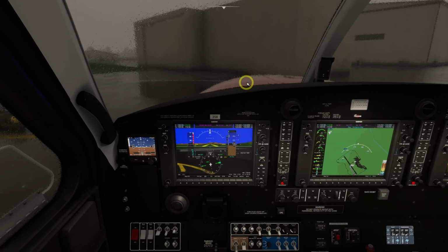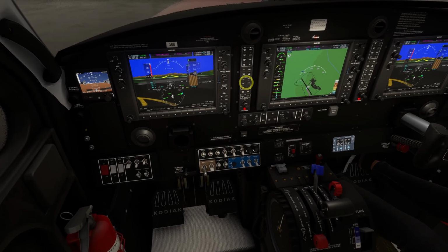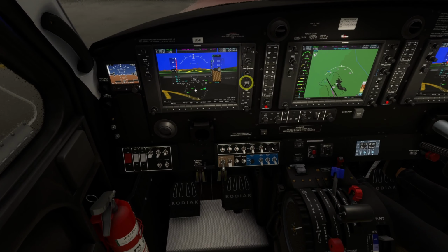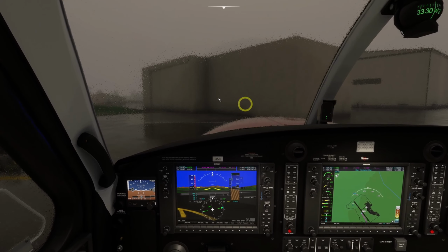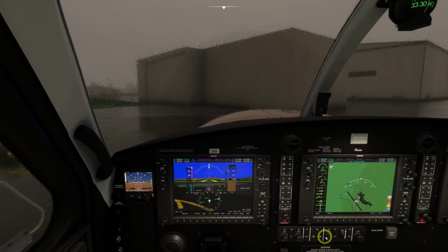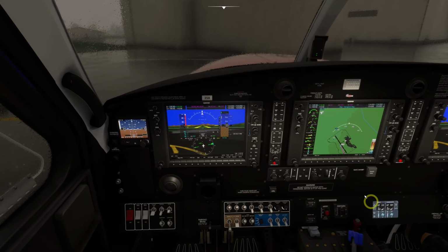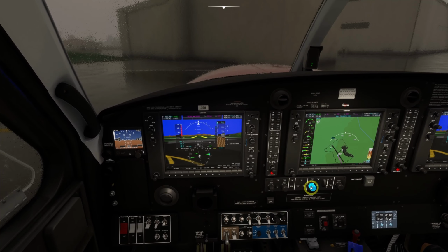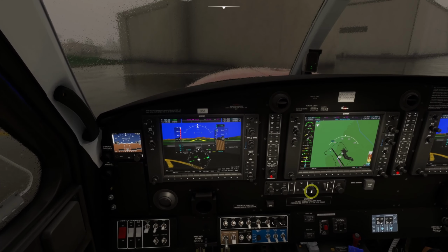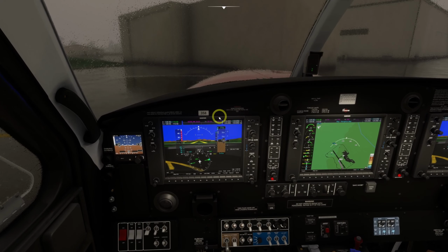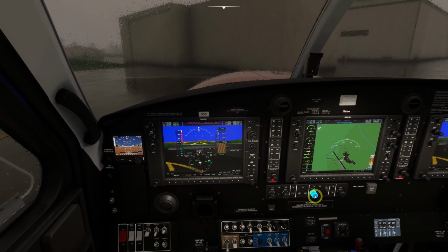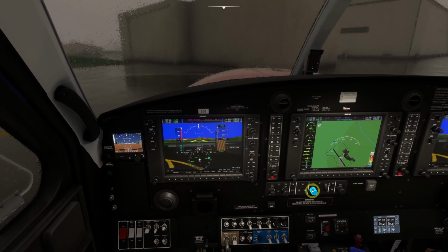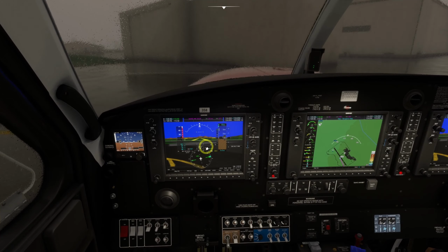Alright, so we can put a stage of flap down now, and I might just trim this aircraft down just there. Now my altitude, what did I say, 5,000 feet, so I'm just going to scroll the alt select to 5,000, and I can see that going up on my primary flight display just here. We're at 27. Keep going, and 5,000 will do. I'm on localizer.